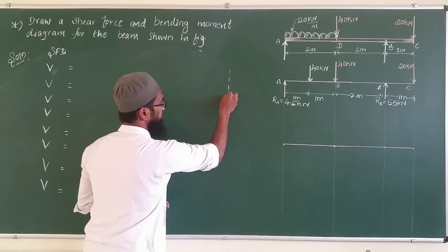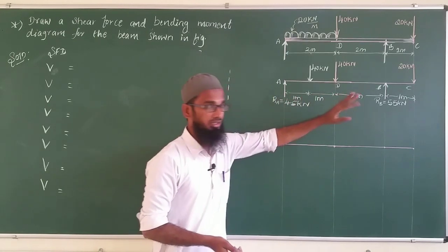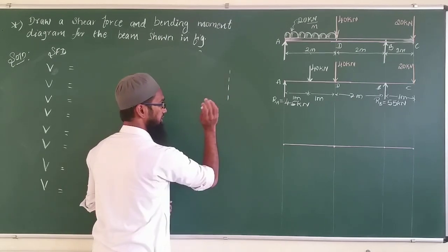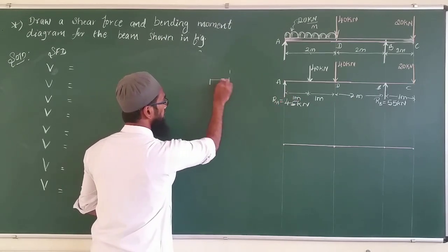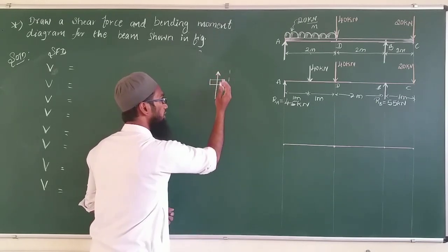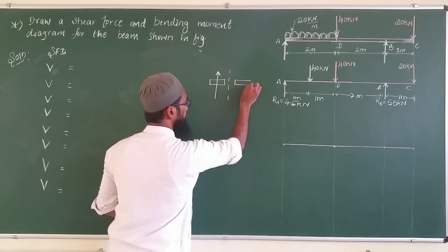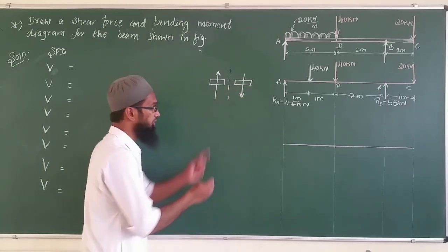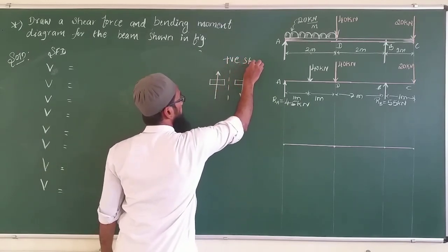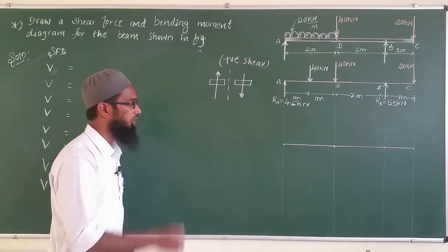Now if I write like this, that is the section here. Section means the reference point like A, D, B or C. This line indicates point A, D, B and C. Now with respect to this point A, or any of these points, if the load is acting in the upward direction on the left of this reference point, similarly, if the load is acting in the downward direction with respect to any reference point, I will consider this a positive shear. If it is acting opposite to that, we will just take the negative. We will just see how it works here.